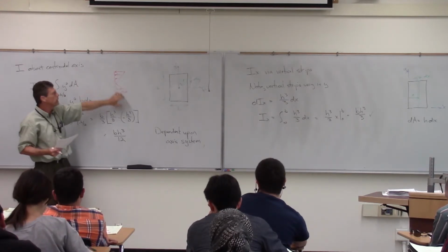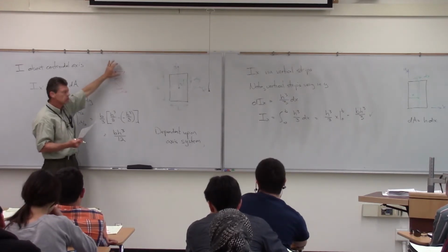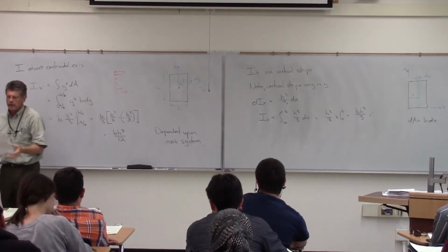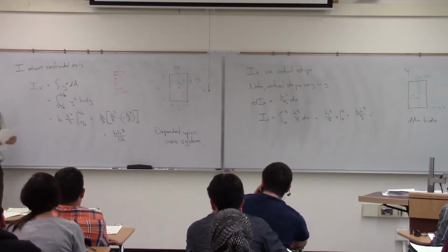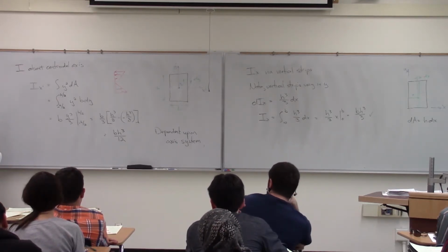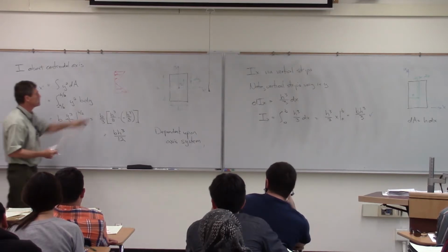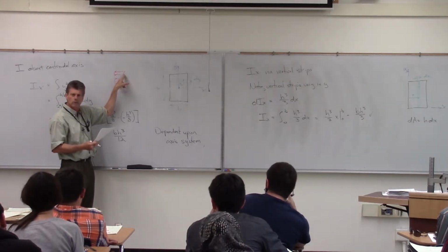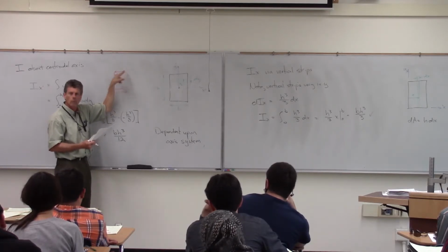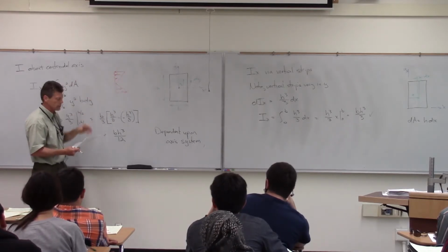So that's why we use this moment of inertia, because it helps us describe how much material I can get out there. And when you look at an eye section, one of your homework problems that you'll do, it'll be looking at a square section versus an eye section using the same area. And what you'll find is that it'll be a much bigger number, but we kind of like that because if all the stresses are out there, then we can carry a lot more. We can put a lot more material out there.